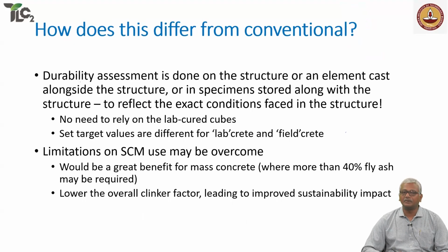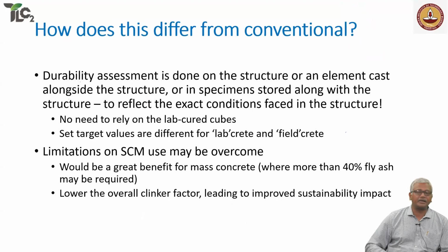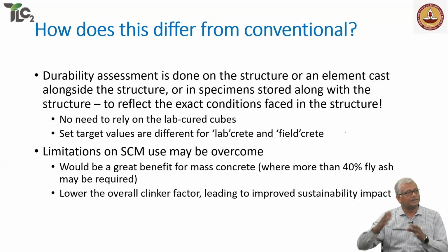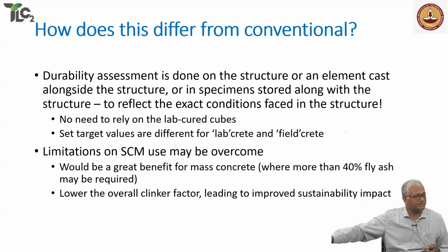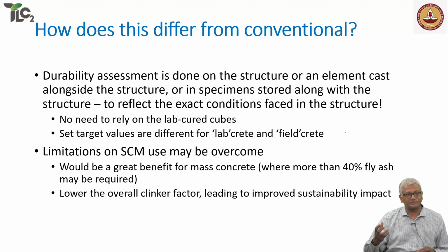I'll give you an example. I was called to inspect a concrete that had not set in 3 days. Okay, this concrete was poured into a column. After 1 day, the foreman saw that the top of the concrete had set, or it looked dry enough, so they removed the formwork. All the concrete simply collapsed, right? So on the 3rd day, I went there, inspected, the concrete was still looking not set, but I could smell the admixture. They had added a lot of admixture, which probably caused a delay in setting.